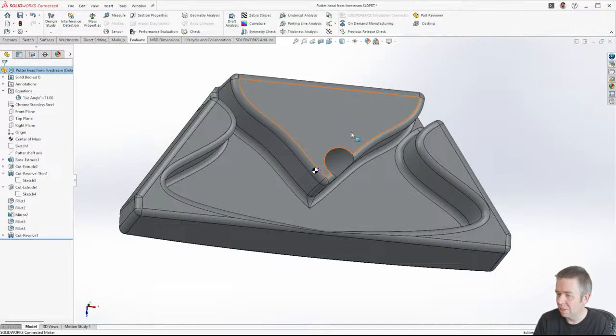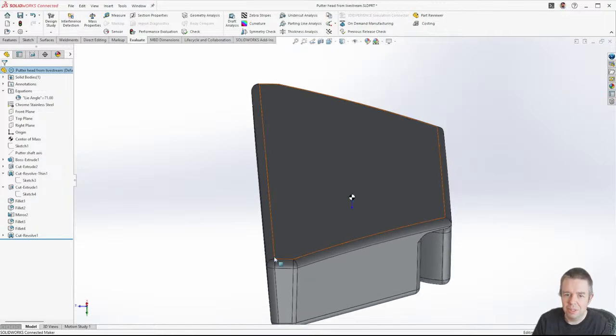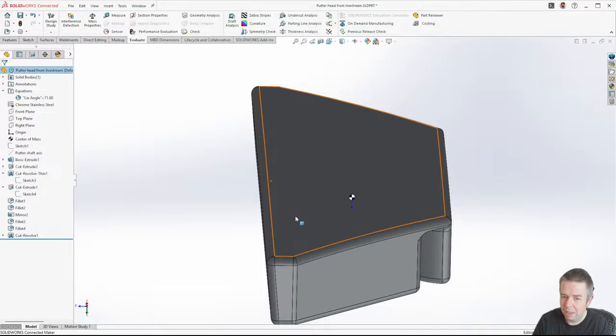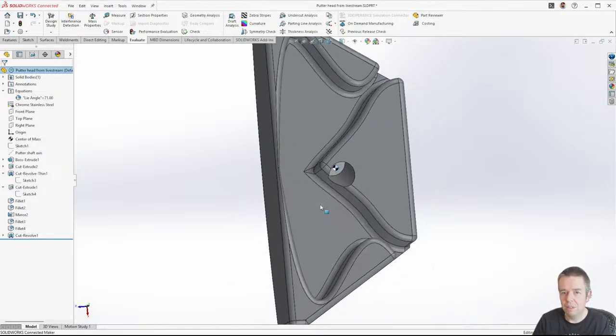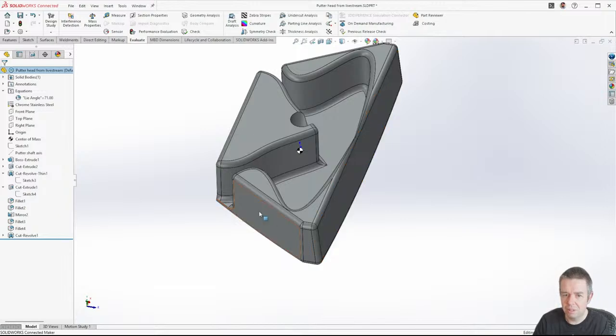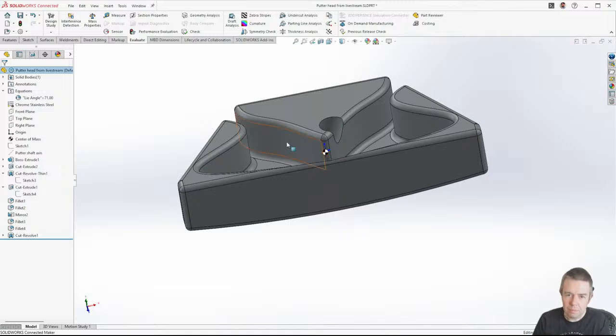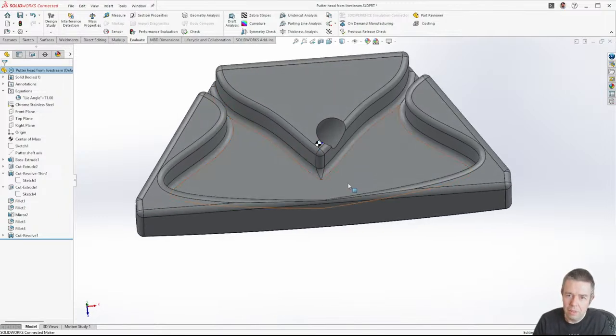being machined. So what I'm thinking I'll do is have this lower surface and this bottom edge perhaps done from just a block of steel, and then I'll design something in on this side that lets me attach it to something else so it can be held from this side, and then we can do all the other 5-ish sides, so front, left, right, back, top, featuring from that fixture point, because that will mean that all of those 5 should be correct in relation to each other.